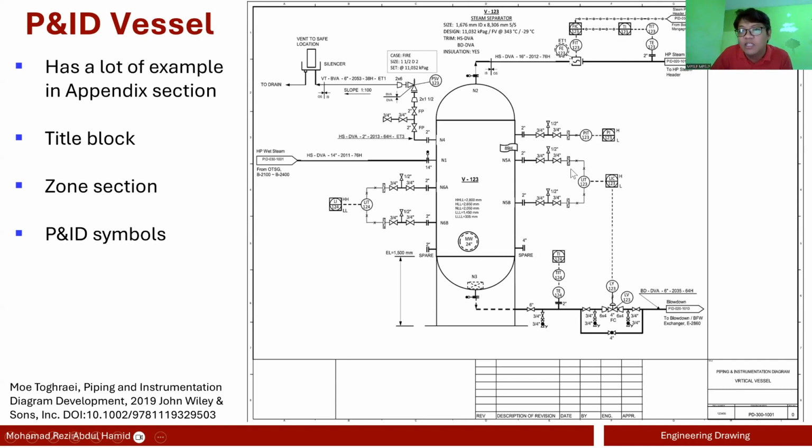So these are capillary lines, capillary signal lines, and these are the electrical signal lines. One interesting thing: in class maybe you only have this control valve alone, right? But in reality, it could be as complex as this. This is not really complex, but there's a purpose why they have this setup. This one is just a line for your liquid, right? And then these are just a temperature indicator and transmitter to detect the temperature of this fluid.